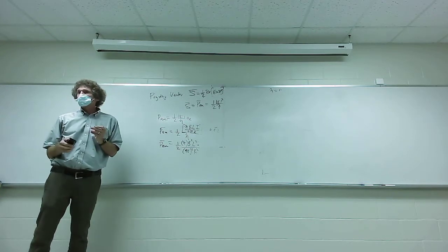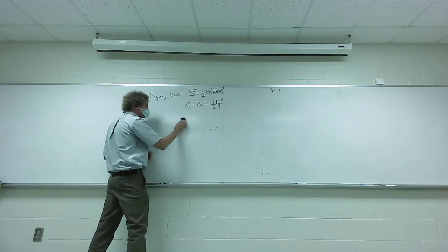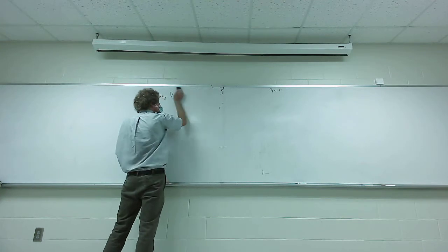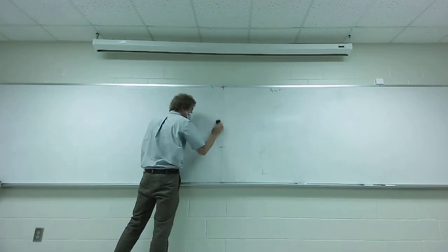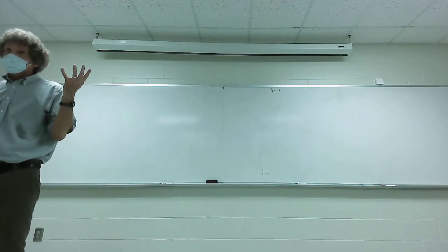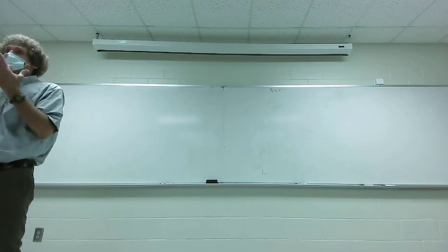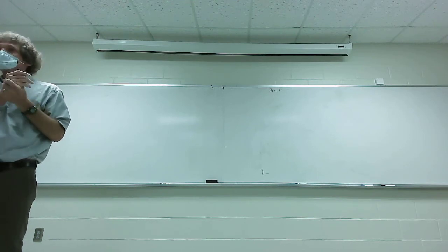You're going to see that they compare everything to an isotropic radiation system. Now, isotropic radiation is just radiation at the same level, the same power density in all directions. A good example is the sun. If you look at the sun, no matter where you are, generally, it has the same power density, or same illumination, same amount of watts per meter squared.